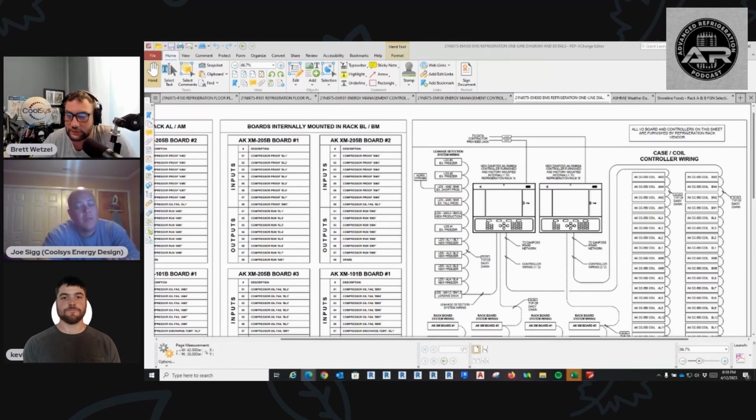But the thing that people are fighting over now is, when it comes to heat reclaim, you get a lot of pumped systems. You get a heat exchanger at the CO2 rack, and then they pump glycol from there into a glycol coil that's in the mechanical unit. Because a lot of the mechanical equipment companies, HVAC system companies, are not actually comfortable putting a CO2 coil in their unit. Really? Because they're worried about getting CO2 out of the space, not putting it into it, if there's a leak in the coil.